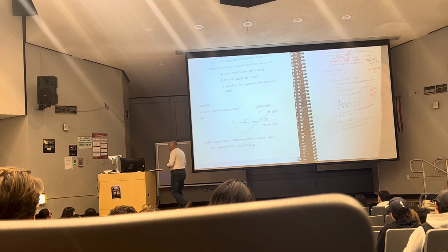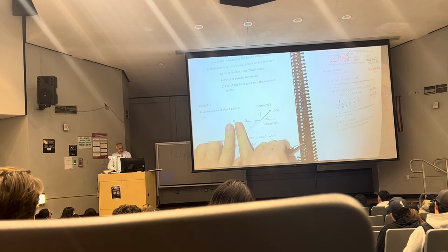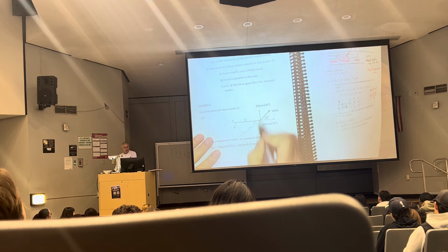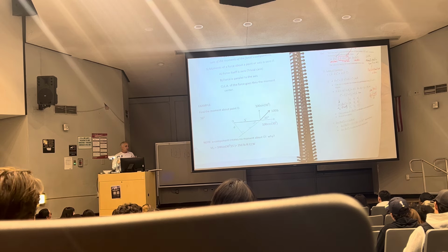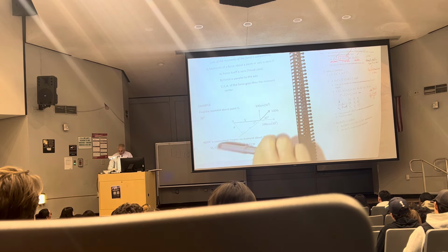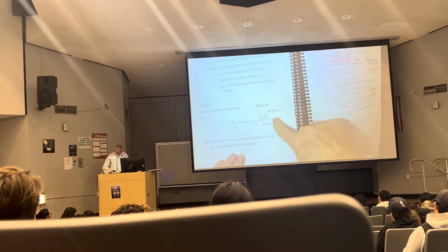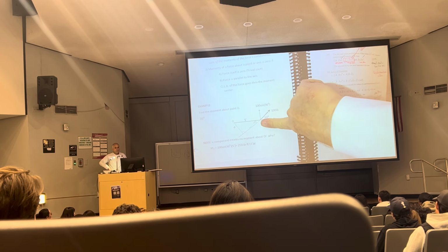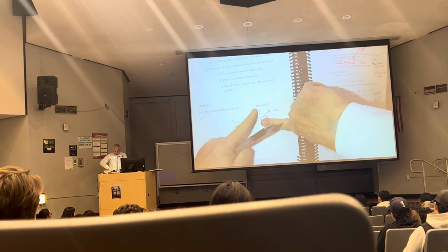Now, if I don't want to go through the hassle of finding this D, I can use Varignon's theorem and say, okay, this is 100 cosine 30, this is 100 sine 30. Agreed? Those are the components. Well, guess what? This component right here goes through the moment center. That sucker creates no moment. What am I left with? 100 sine 30 times the distance of 5.